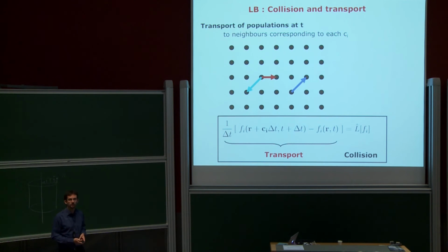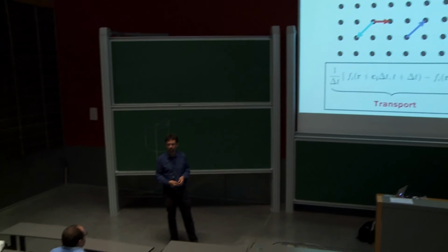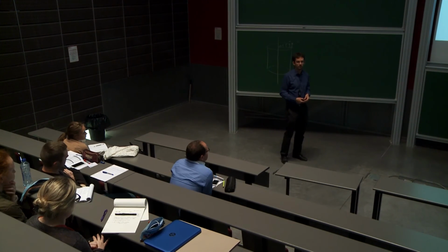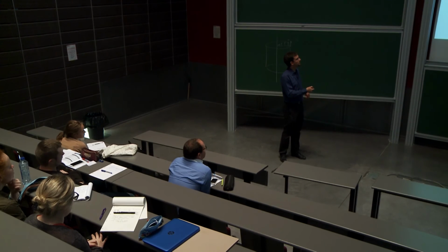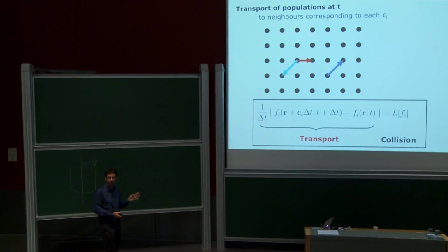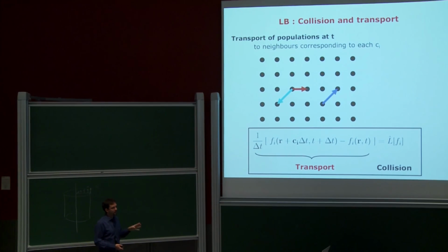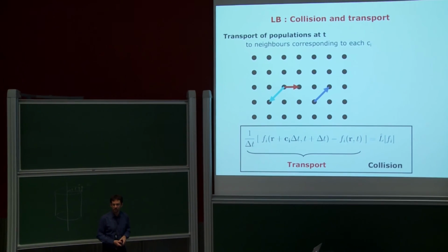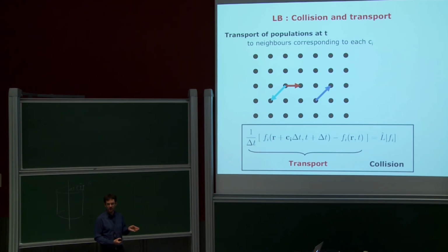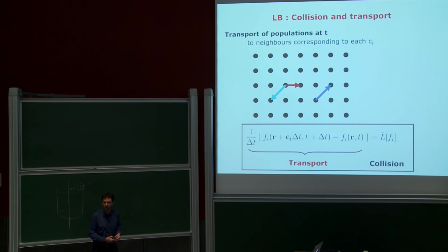Any other question about simple fluids? Yes? About your grid, can you imagine to have irregular patterns? Yes, so most algorithms would work with the lattices I've shown, very regular. Nowadays, it's possible to make irregular grids, but then you have to think much harder about the weights corresponding to each velocity and how to compute the moments from the velocities, but it is nowadays possible.